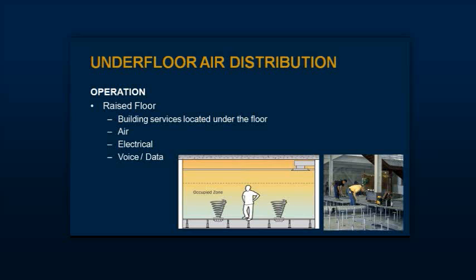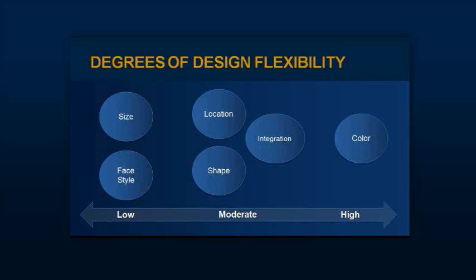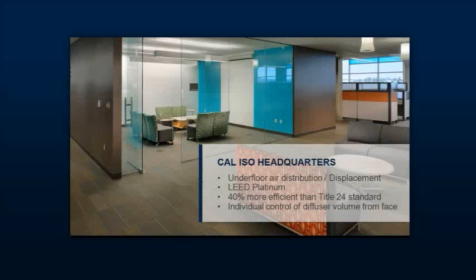And my goal, of course, is that I have occupants that consider themselves thermally comfortable. My goal is to make sure that I have fully mixed the space, I fully cover the space, and I achieve at least 80% thermal comfort. Now, it's a sad indictment of our design approach over the decades since Willis Carrier introduced forced air systems in 1903. Our goal has always been at least 80% of the occupants expressing thermal comfort or satisfaction with their environment.